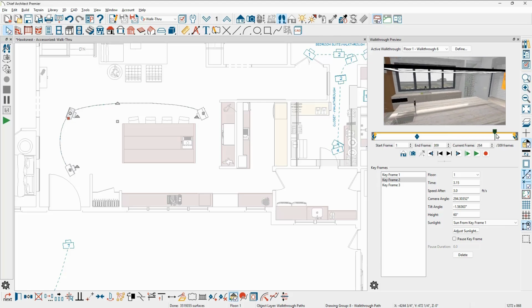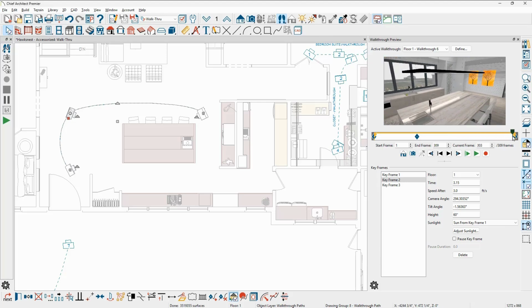So what's going to happen is the camera is going to raise in height between frame 2 and 3 over the course of about 24 inches. It will move the camera in a linear fashion in between those two keyframes. In between each of the keyframes, notice that between keyframe number 2 and number 3, there is a speed after the camera. For each of your cameras, with the exception of the very last frame, you can control the speed after your camera. So if you want to slow something down, speed something up, you can do that in between